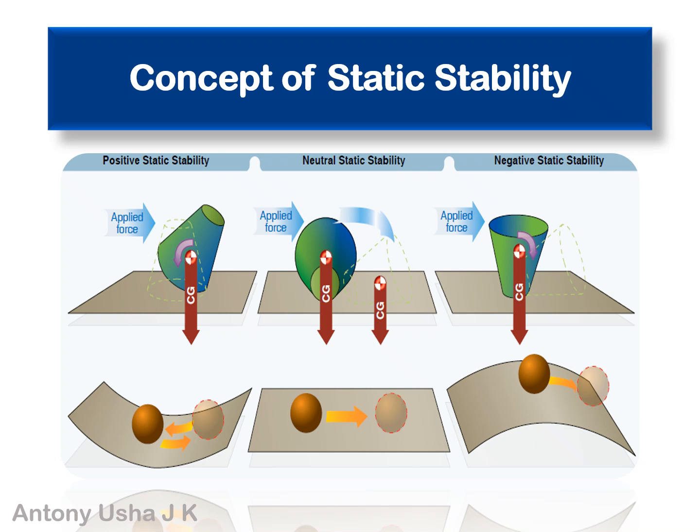And here comes neutral static stability, that is in the middle picture. The aircraft has neutral static stability if, after a disturbance, it neither returns to its original position nor diverges further. It remains in the new attitude without generating restoring or amplifying forces or moments. So it is generating but not amplifying any force or moment. So it is neutral static stability.